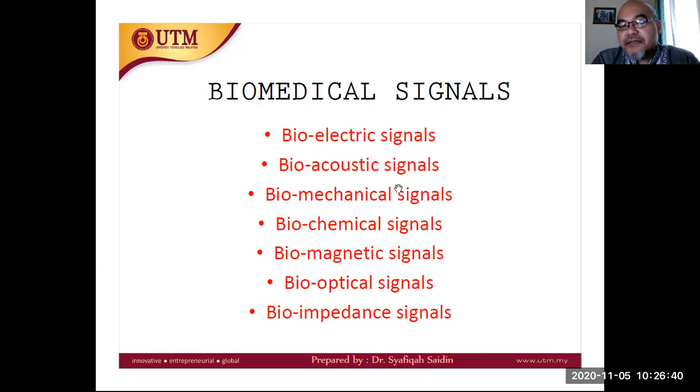Biomechanical signals also, we have mentioned a little bit, say for gait analysis, for muscular analysis, etc., is usually in the form of a biomechanical signal. I myself, in the last 3 to 4 years in SGU, have also been developing sensors and instrumentation to capture this biomechanical signal, using carbon nanotube coated thread to capture the mechanical strain of the muscle, with the purpose similar to EMG, to capture the muscular activation.